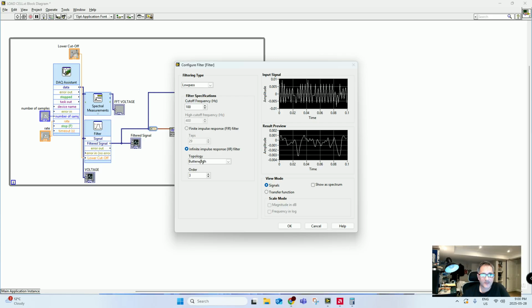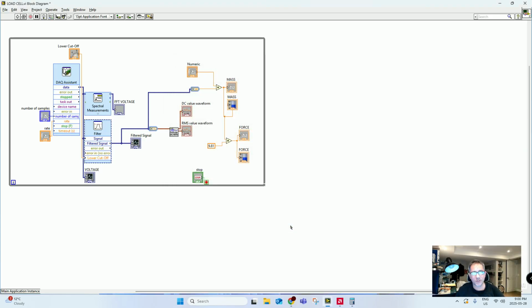I chose a low pass Butterworth third order, which is a very common filter, especially for those data acquisition systems that capture this kind of signal, because the load cell is a device that is subjected to different oscillations, noise, disturbance, and also temperature variation, and electrical signal fluctuation due to the components, which are not ideal. They are not perfect, and nothing is perfect. So especially in the components you have several oscillations.